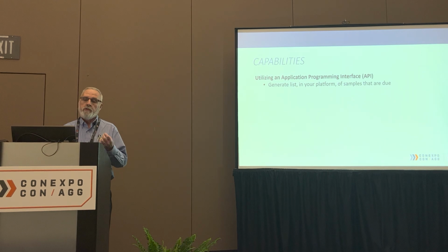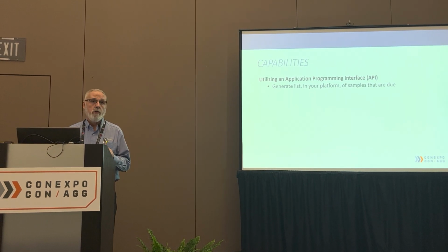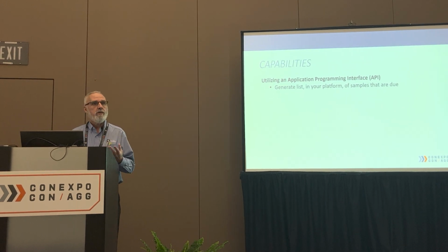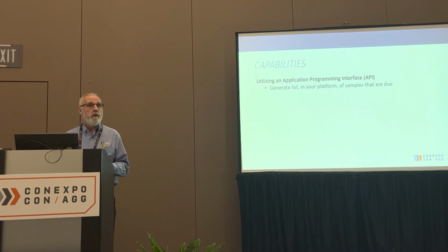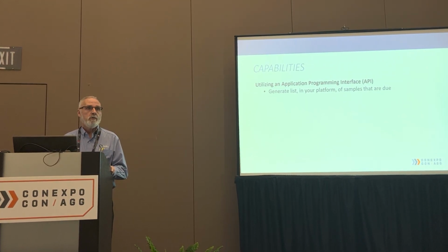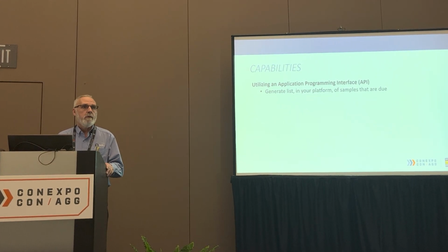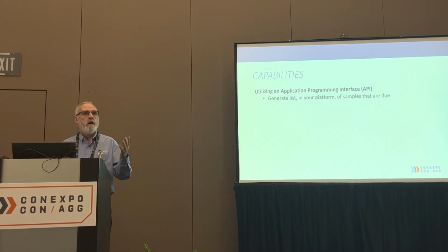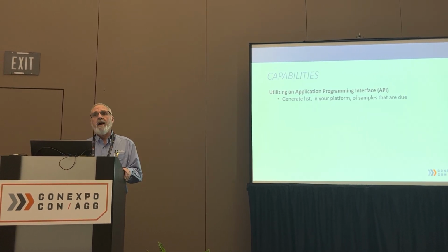The laboratory says, all right, this was the last date that we received a sample on that component. And then we ask the customer, how long does it take you to reach in days that 250 hours? The customer says, well, on average, it takes us 21 days. So the laboratory will look at the last sample received and say, okay, in 21 days you're due for another sample. But how accurate is that?